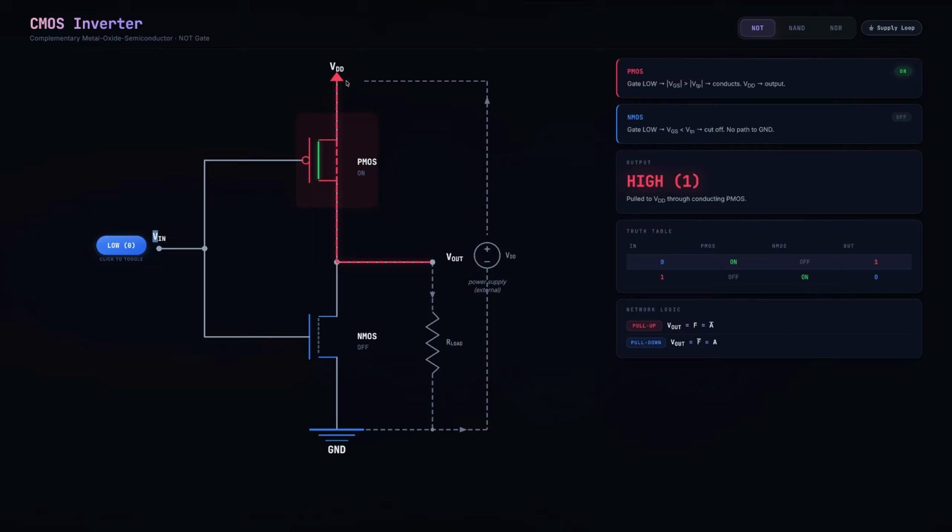Because this is connected to VDD, this output level is a high voltage, and current would actually flow through here. Now, because this was a low, that's what turned this on. Look what happens when we turn this to a high voltage. With a high voltage, the bubble here means that you take a high voltage, hit the bubble, it's like a low voltage, and it turns this off. So this PMOS transistor is turned off, and there's no connection between VDD and the output here.